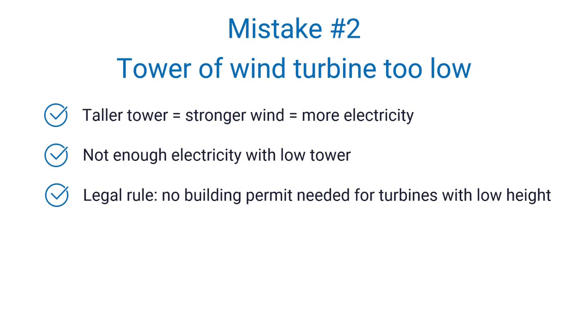But anyhow, the house owner might think, well, great, I do not want to apply for a building permit, so I just use a low tower. But you will be disappointed if the turbine does not produce the power you intended when the wind is not strong enough because of a low tower.